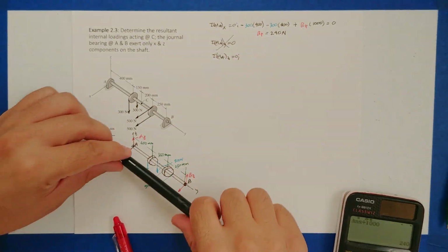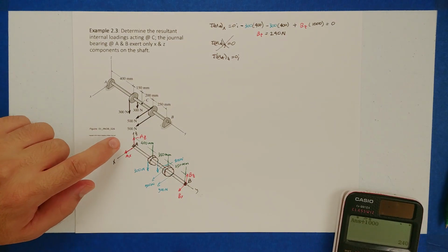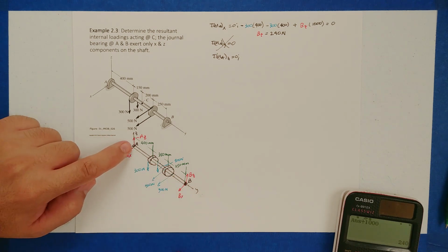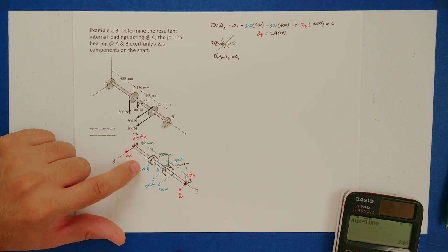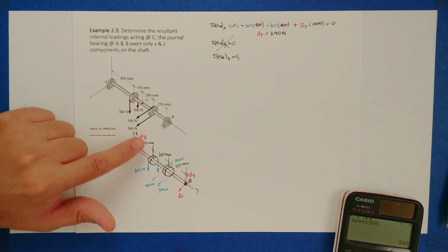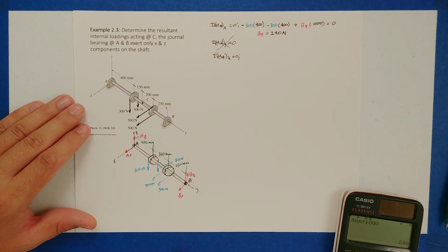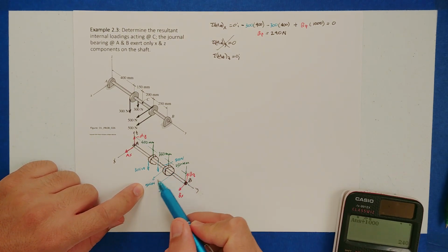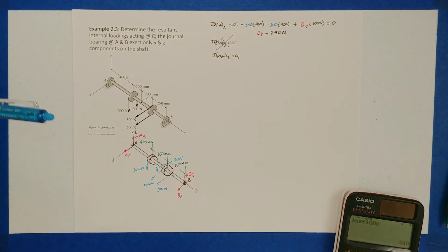So now we're looking for stuff that's going to rotate in this direction. So let's go ahead and start. We're starting at point A. I'm going to start here and I'm going to sweep away from point A. Right? AX, AC are at point A. They're not going to generate a moment at point A. The 300 Newton forces are in the negative z direction. A force in the z does not cause a rotation about the z. So those two are not going to show up. Instead, what we're going to have is these 500 Newton forces, right? They're pointing towards the positive x. So I hope you can see that this is going to make it swing like so.